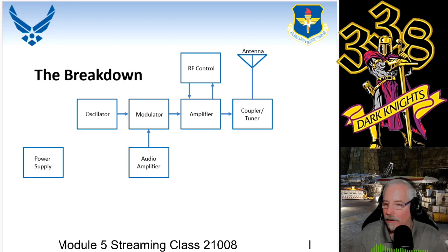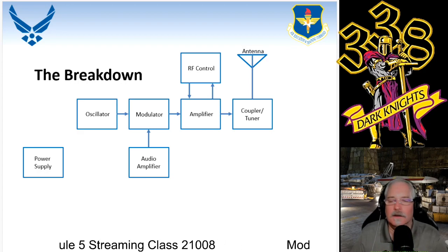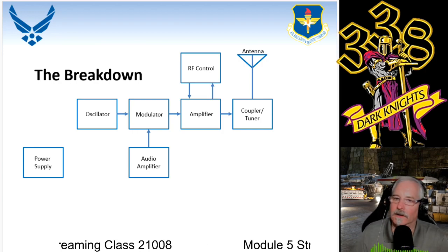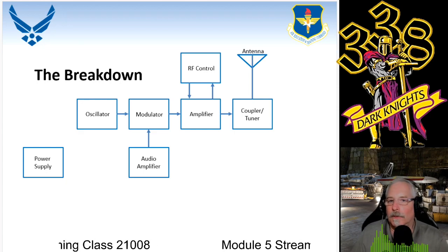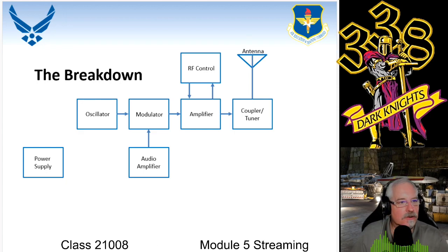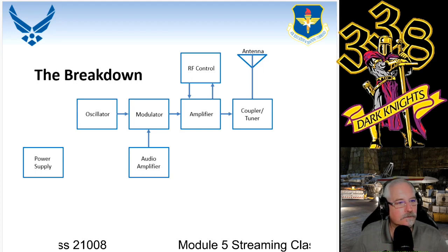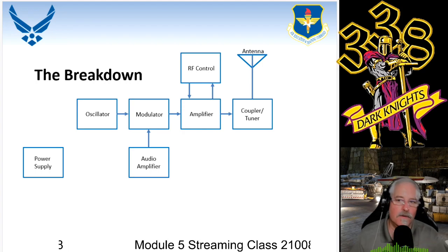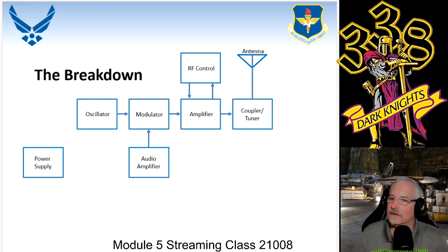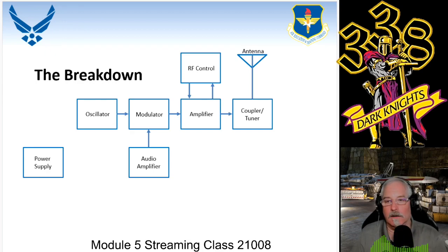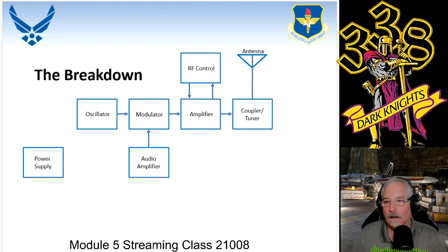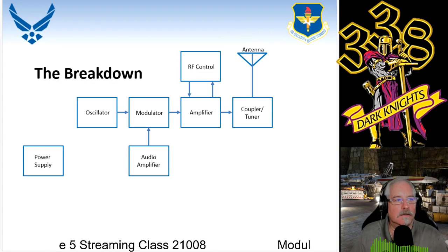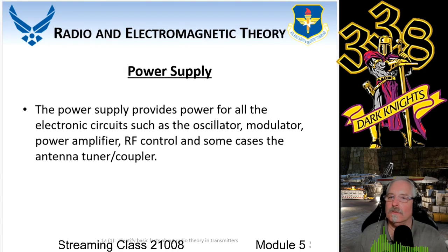We're not going to get into component level, even though I could, but it doesn't make any sense to do so since most of the devices now are either line replaceable units or just remove and replace the whole radio. But you got to determine whether or not it's the radio itself or if it is something that's causing the problem within the radio, like the cable, the antenna, connector on your mic, and so forth and so on. So let's break this down into each individual module.